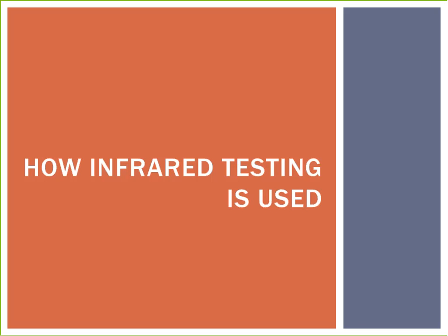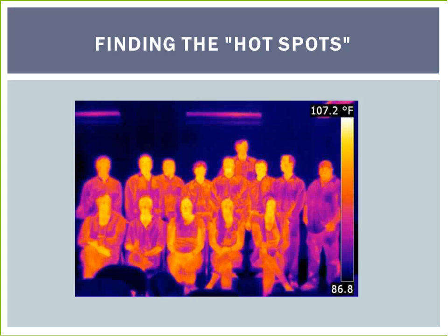Next, we will discuss how infrared testing is used. Infrared thermography is a non-destructive technique for detecting temperature differentials that may indicate problems such as loose electrical connections or excessive friction in machinery and mechanical systems.